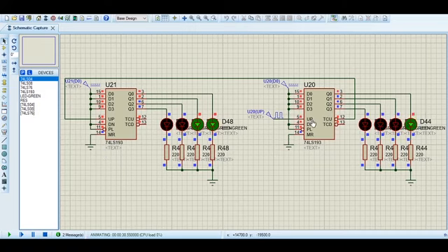The up pin of this chip is attached to a clock generator, and the up pin of this chip is attached to the carry out or terminal count up of this chip, and both their DN pins are attached to a 1 input. Therefore, both counters would count up.